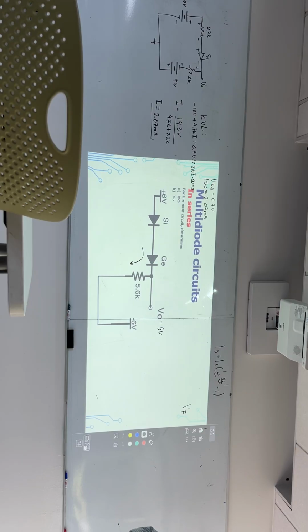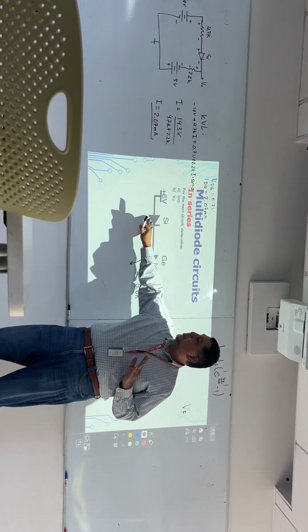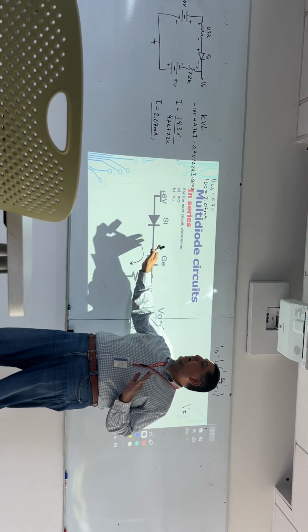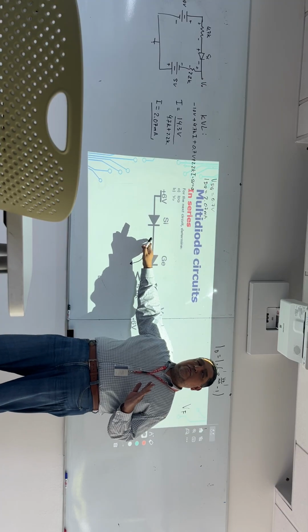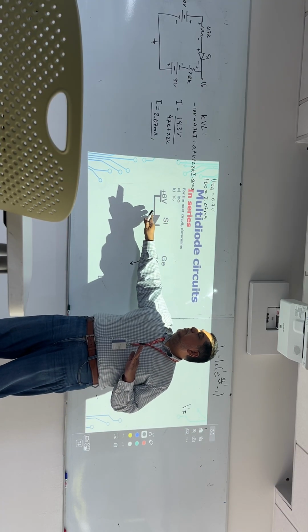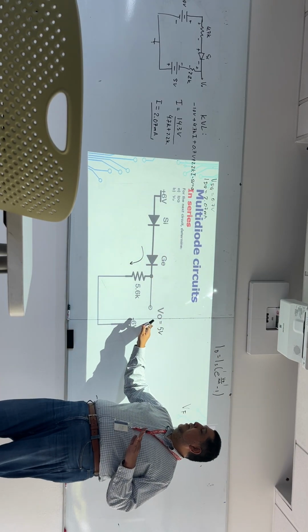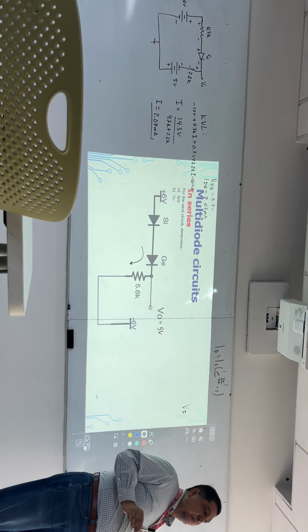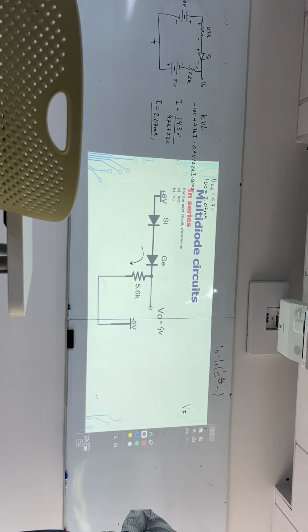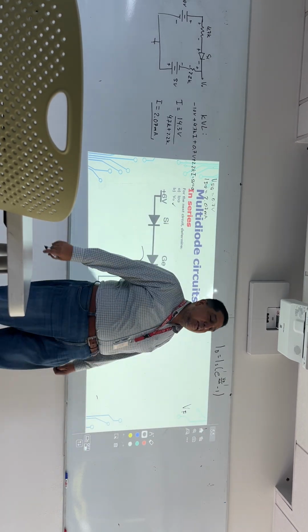Yes, piece of cake, hopefully. So I repeat, identify this voltage, going towards the direction of the current, I begin subtracting the voltages that I know. 6 minus 0.7 minus 0.3 will be 5. There's no need to write the whole KVL equation. Now I have V0, check. Now, how can I get IDQ?